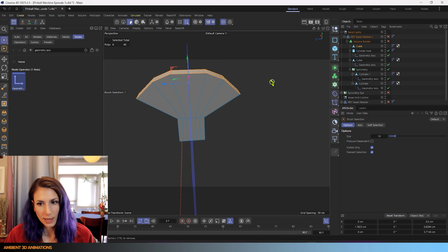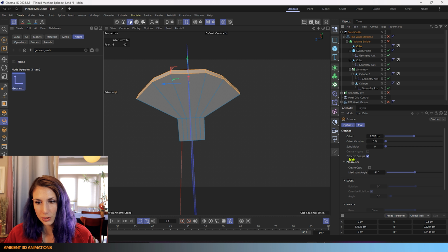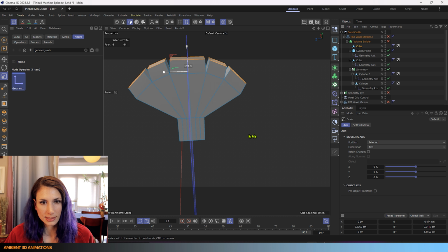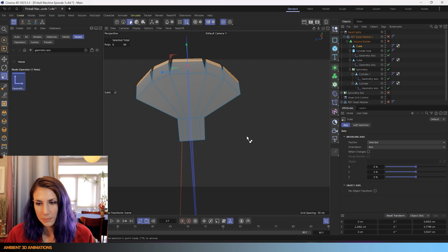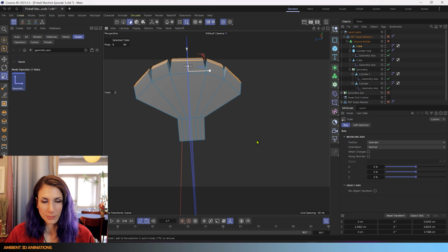Now I want to have these polygons selected, but I want to do something a little bit different. When I extrude them using MT, I want to turn off preserve polygon groups so that I am extruding each one of these individually. And then I can hit T and scale them in at the top. But I want to do this per polygon. So I want to scale these in, but you can see that they're being scaled in all as a group, which I don't like.